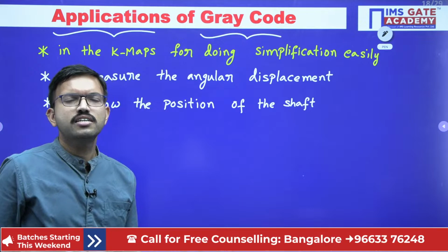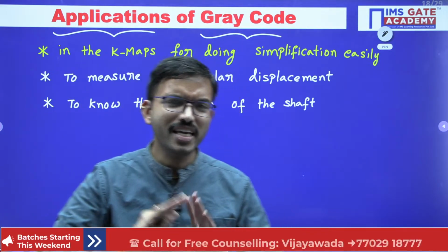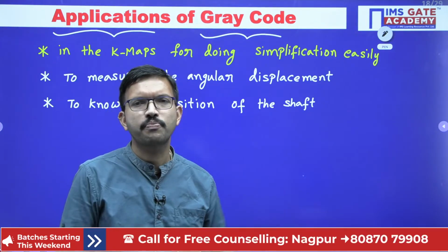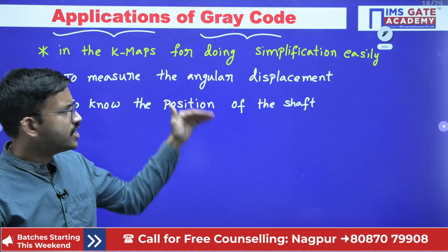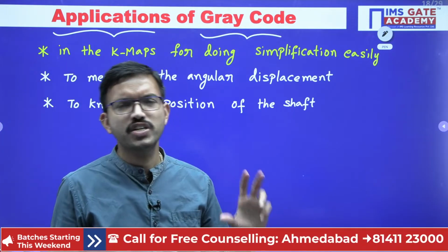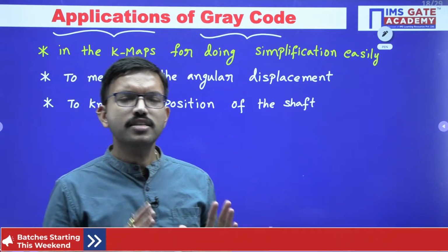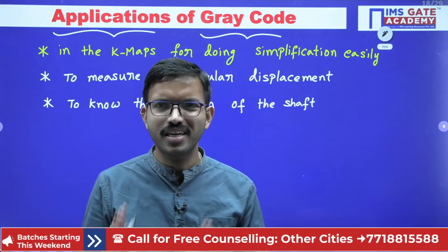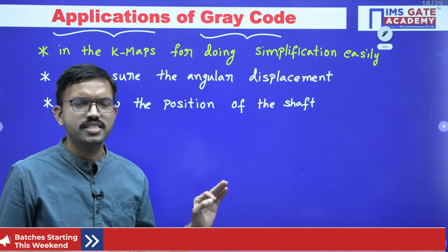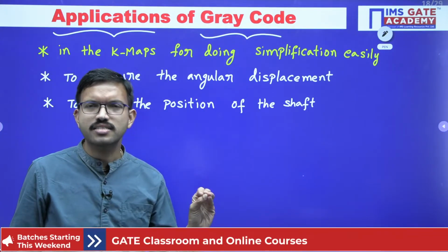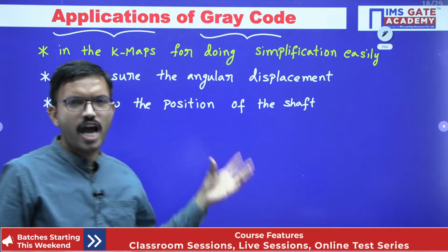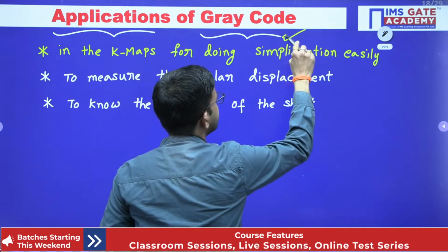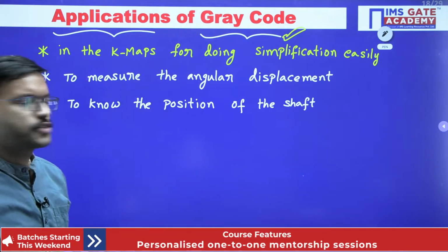And not only that, whenever you are getting any ambiguity because of unsigned or normal sequential code, if you are considering binary numbers in the sequential form, and because of that sequential form you are getting any errors or having any ambiguity regarding your results, in all such cases, in order to get the correct results or to avoid all such ambiguities, in all such applications you can use the gray code.